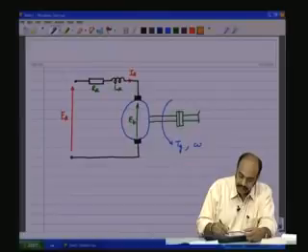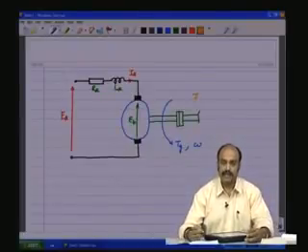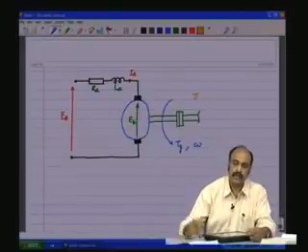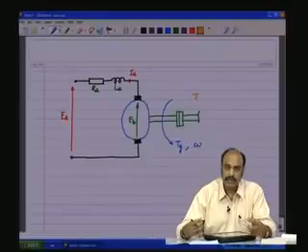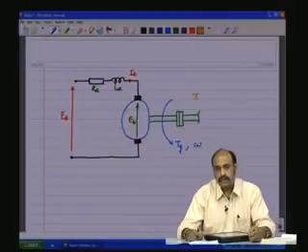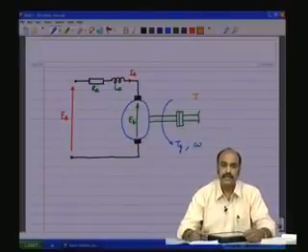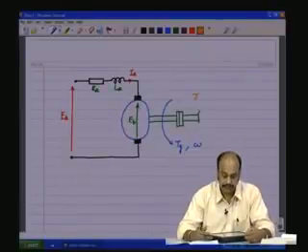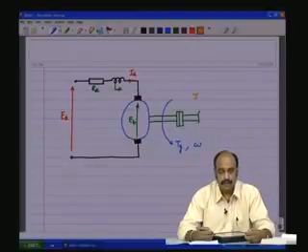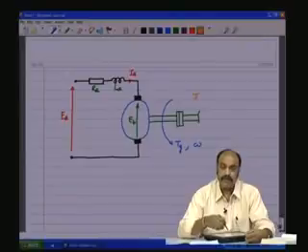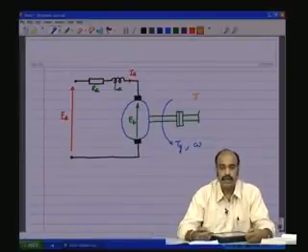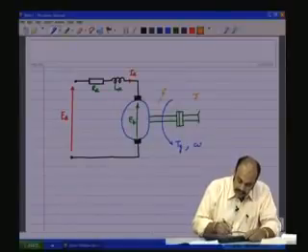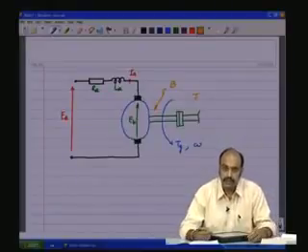its own load, or the reflected inertia J, which is like the mass of a vehicle or the mass of the load or a mass of a very big wheel, which has an inertia to it, and when it is rotating it gets stored in the kinetic form, and that is called the inertial energy, which is stored by virtue of an object being in motion. Therefore, J, or the inertial parameter, is similar to L, the inductive parameter, and therefore, the state variable in the case of the mechanical domain which is involved with the parameter J would be omega, the speed. There could also be at the bearings some friction associated, and we will call it friction B.